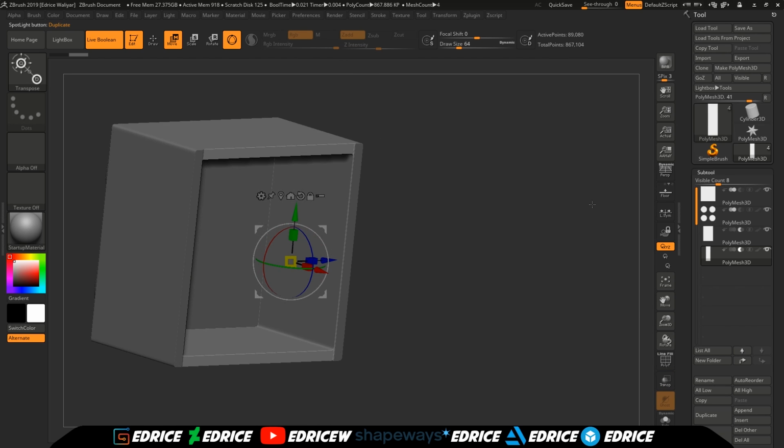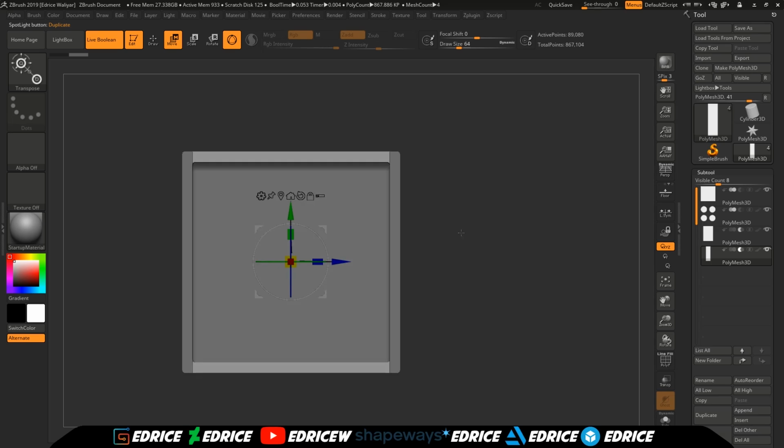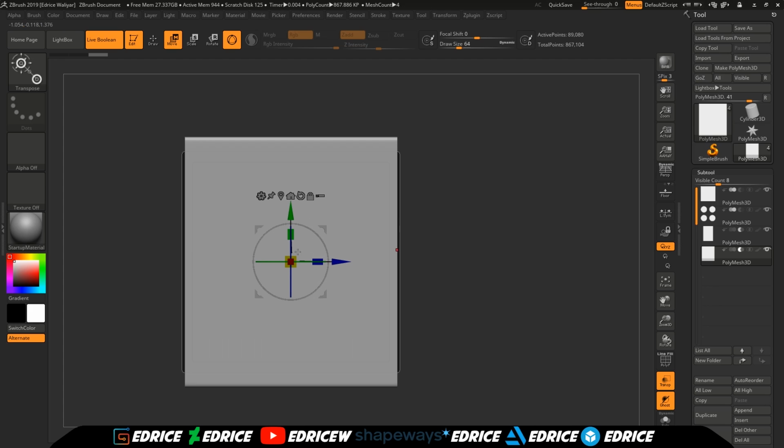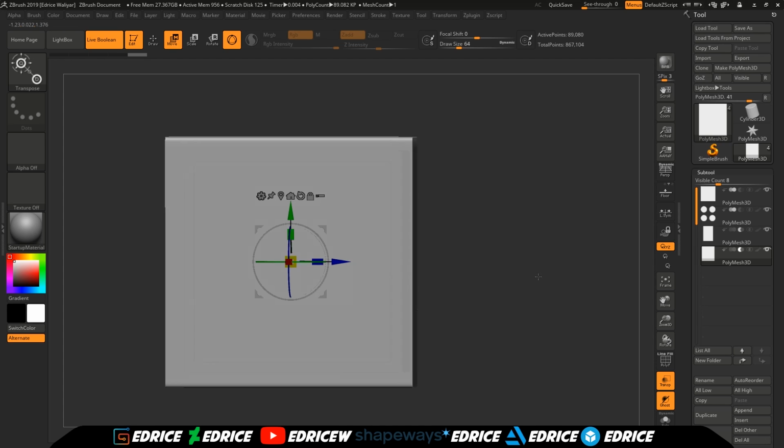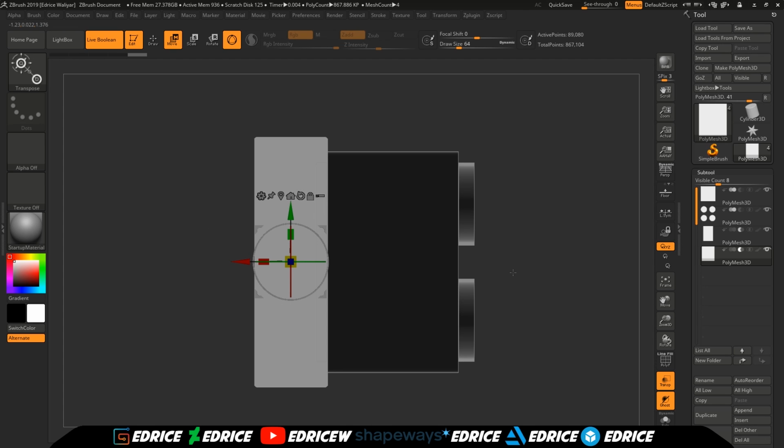And this is not, we didn't make it thick enough, so if you turn on transparency, you can see that the extrusion wasn't wide enough, so it's not an issue, just scale it bigger. And this is going to be our clip plane. So whatever we do from now on, we will know that the bottom of our little Lego cube is going to be perfectly flat whatever we do.